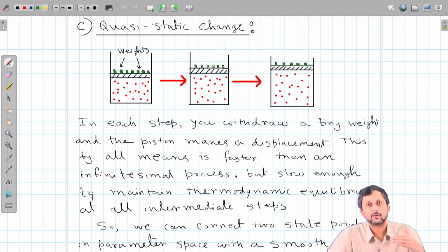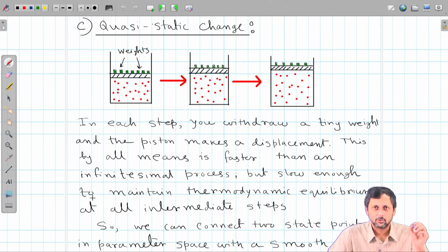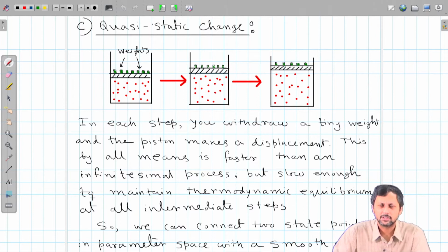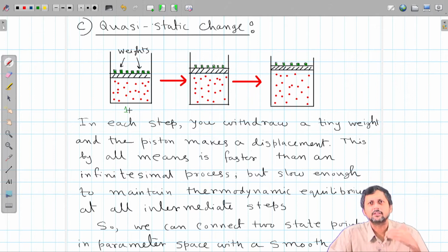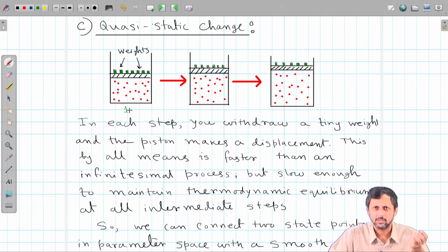Let us say we have a certain amount of gas enclosed inside this piston, and we have small weights placed on the piston plate. Now this weight in the first position, in this case position 1, is exactly equal to the internal pressure. It is sufficient to balance the internal pressure, and there the piston is in a stationary position. These weights are small, finitely small, not infinitely small, maybe few grams, maybe tens of grams, depending on the situation, but these are small weights.